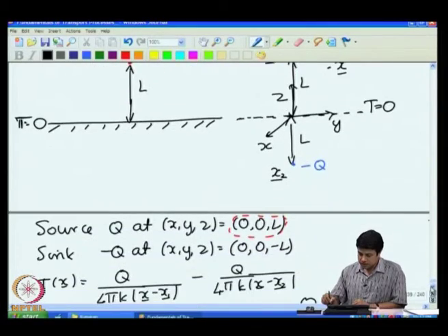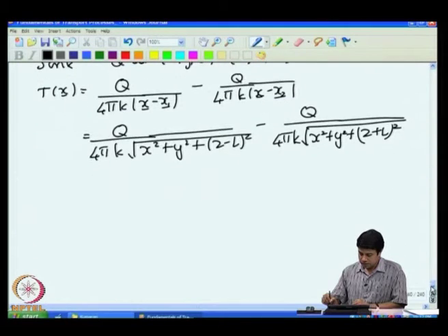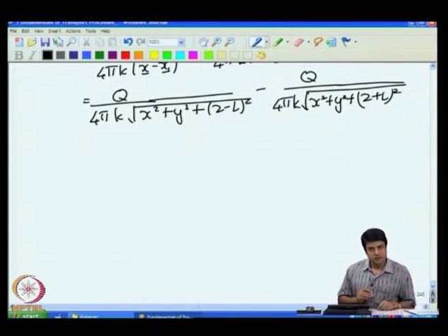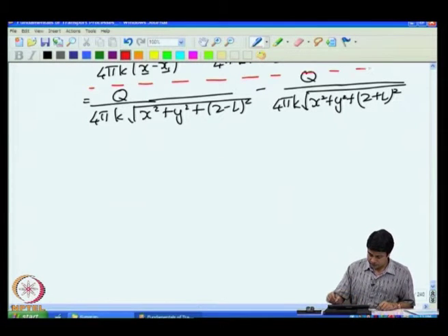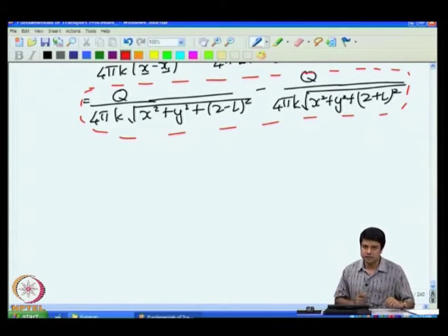So, this was with temperature equal to 0 at the surface. In many practical applications, one will have a heat flux equal to 0 at the surface. So, this is the Green's function for 0 temperature at the surface, or for a fixed temperature at the surface, because I can always define a rescaled temperature in such a way that the temperature at that surface is equal to 0.